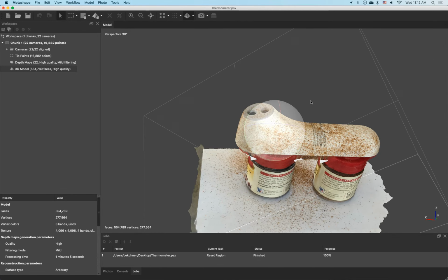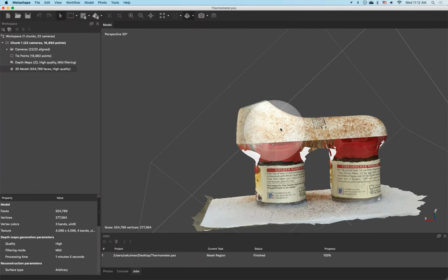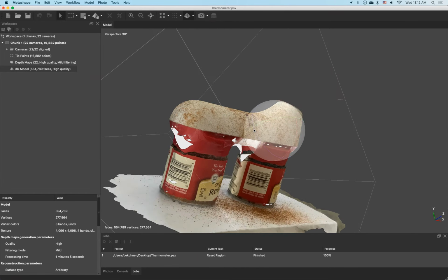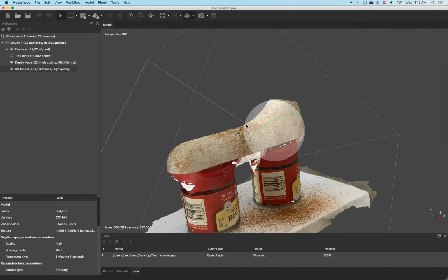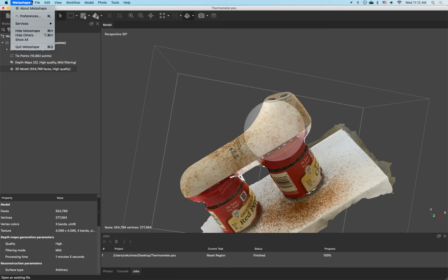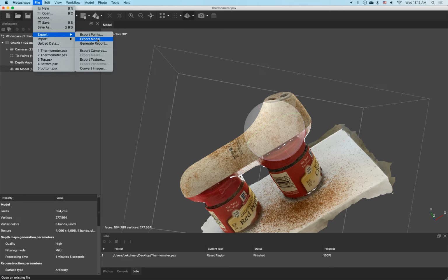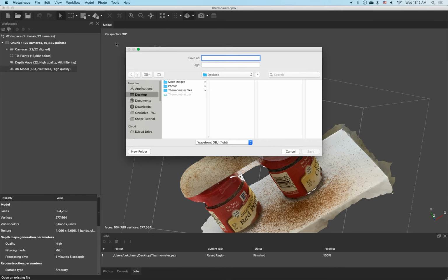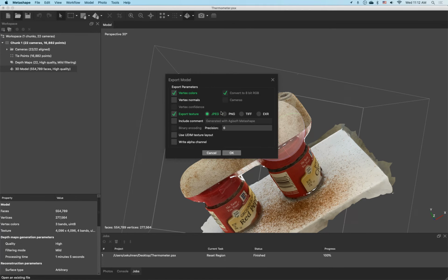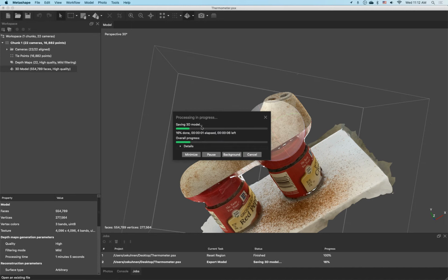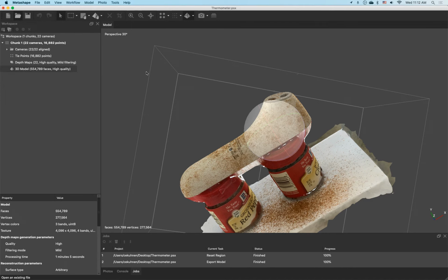That's also why I like doing this type of modeling in Blender, not in Fusion, because Fusion can import the geometry, but it skips the texture, which is really annoying. The texture here really helps in understanding where the seam is. Okay, very good. When you're done, all we have to do is go to export and export model. Just export it there as Wavefront OBJ, save, and this is all correct. Click OK, and it takes a moment, and there it is.